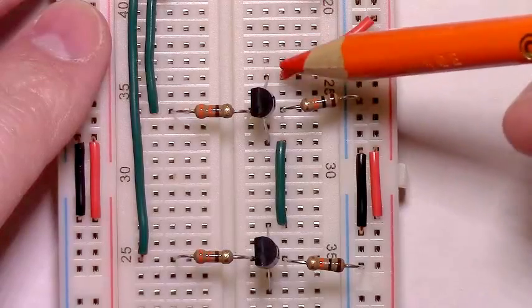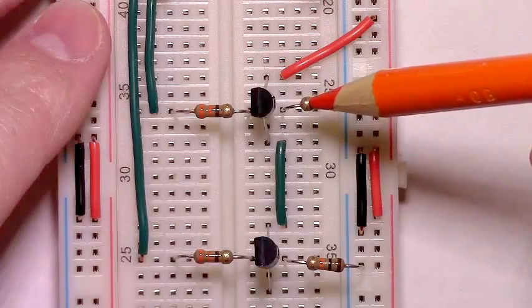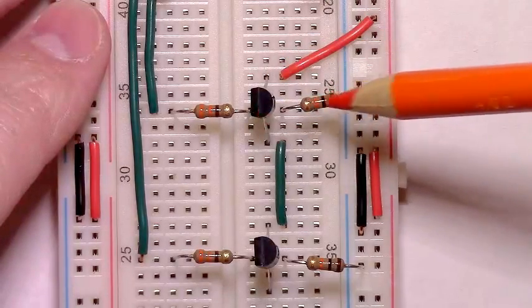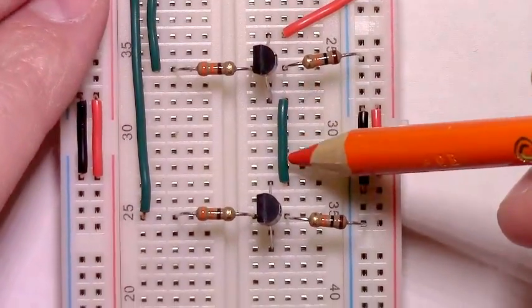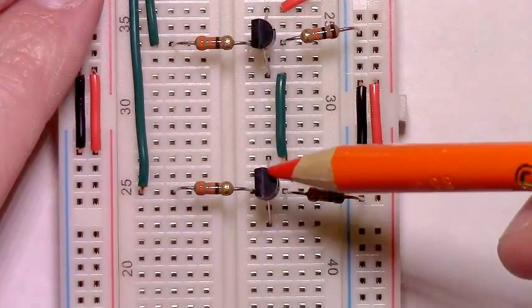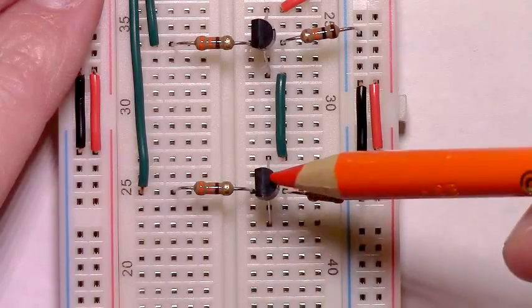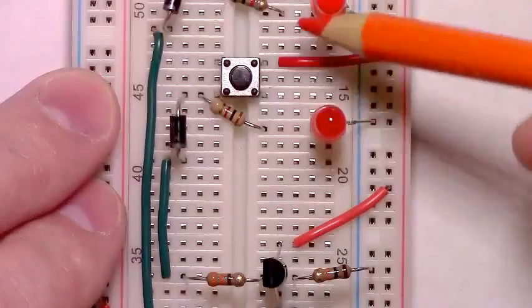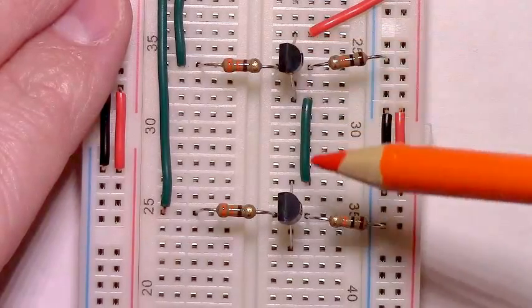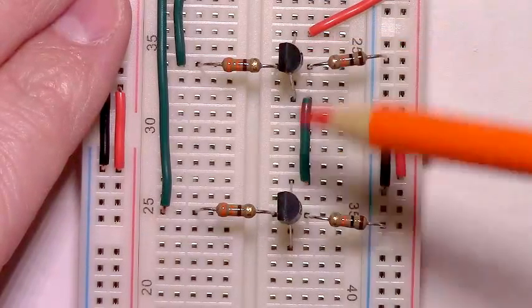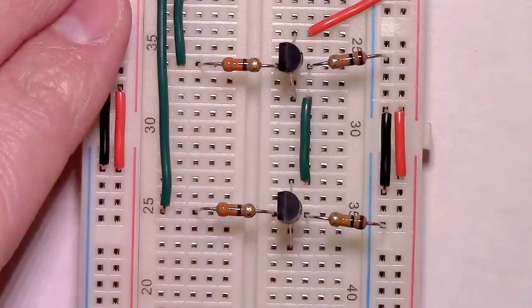So now these two PNP transistors are in series. VCC is sitting at the emitter of the first PNP, and given that its base will be pulled down to ground through this 10K, it'll conduct through this wire. The base of this PNP is pulled down through a 10K, so it'll conduct as well when neither of the momentary buttons is being pushed. So they're in series. Imagine two switches being flipped on in a single line of wire.